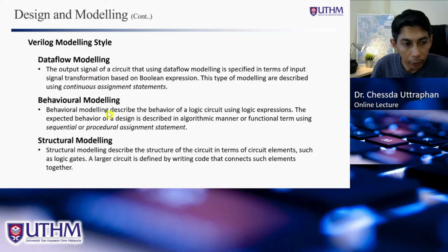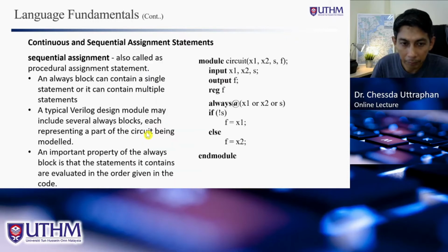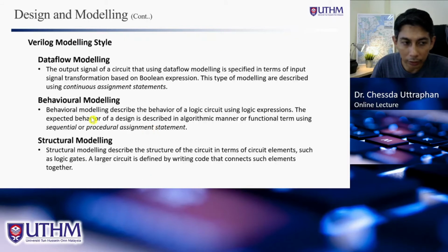But when you describe your circuit using the behavior of the circuit, and you use sequential or procedural assignment statements, meaning you write your code this way, it means that you design your circuit using behavioral modeling, right?